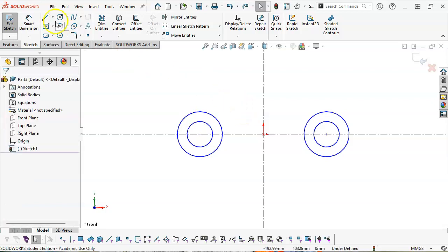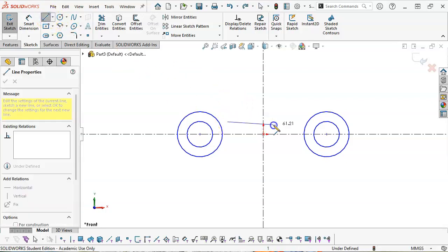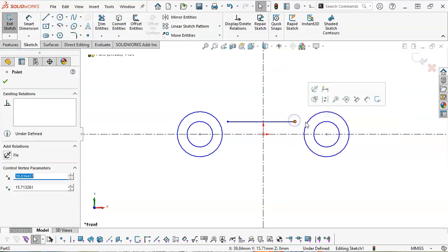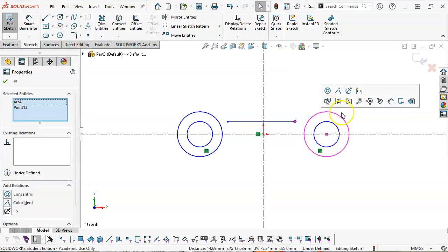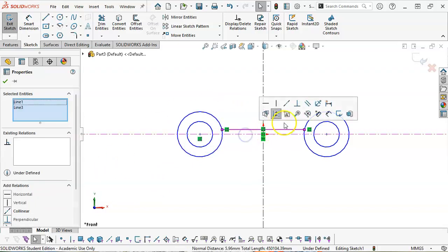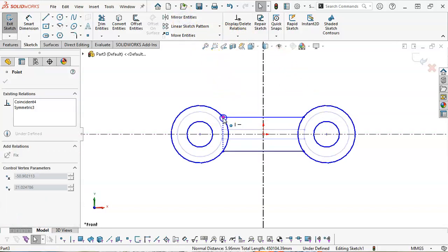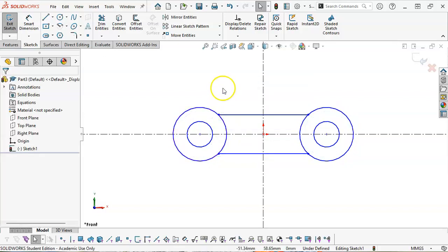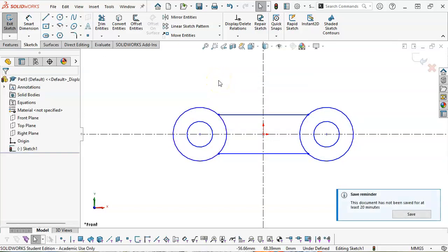So I'm going to give that a Control Z, and if that happens, just draw your circle kind of out. It usually does not have a problem terminating at the circumference of a circle. It's when you start. So if we go coincident and select, control select, coincident, then I can mirror those across the horizontal, and they will kind of stretch and shrink because we haven't put any dimensions on these yet.